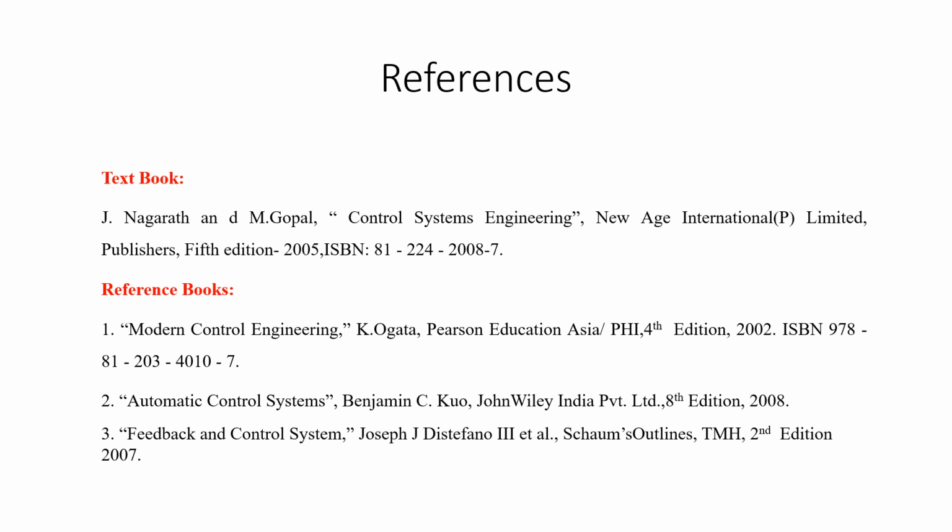And in the 7th rule, you have learned about reduction of the feedback loop by using the open loop transfer function G and the feedback transfer function H. And a few examples on this were shown to you in today's session. So try to take a different block diagram representation like this and apply the reduction rules and try to simplify the given block diagram and evaluate the transfer function for a given control system.